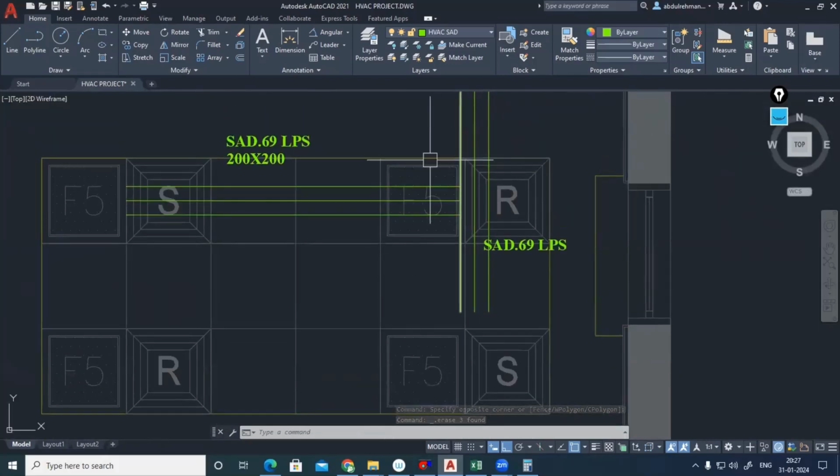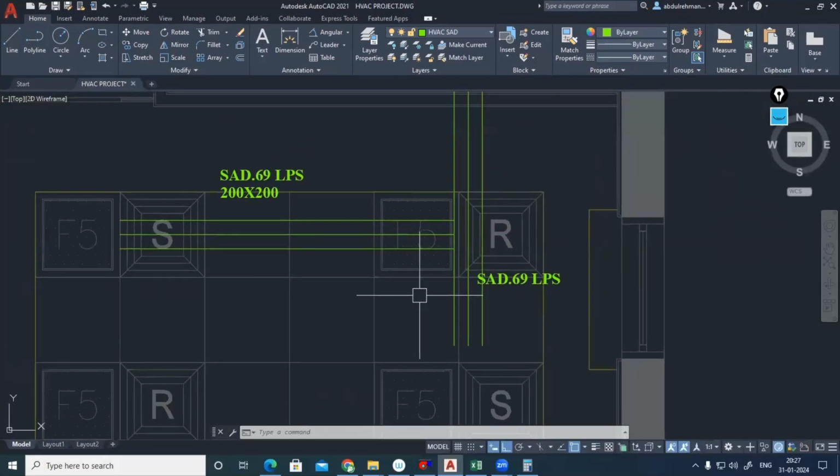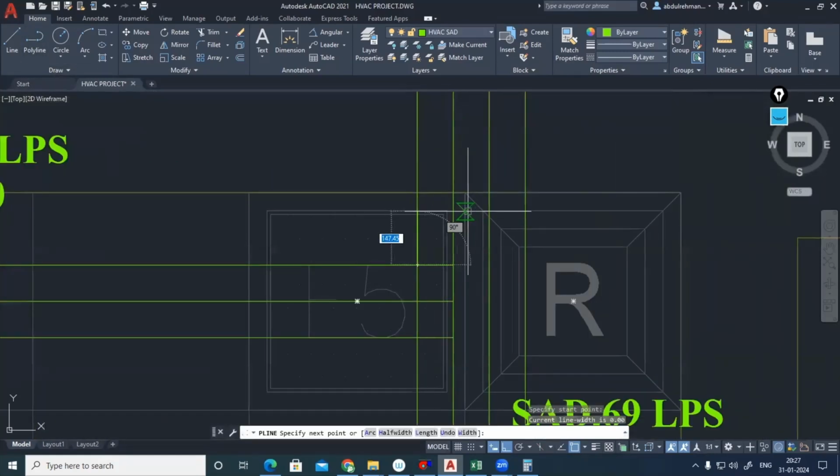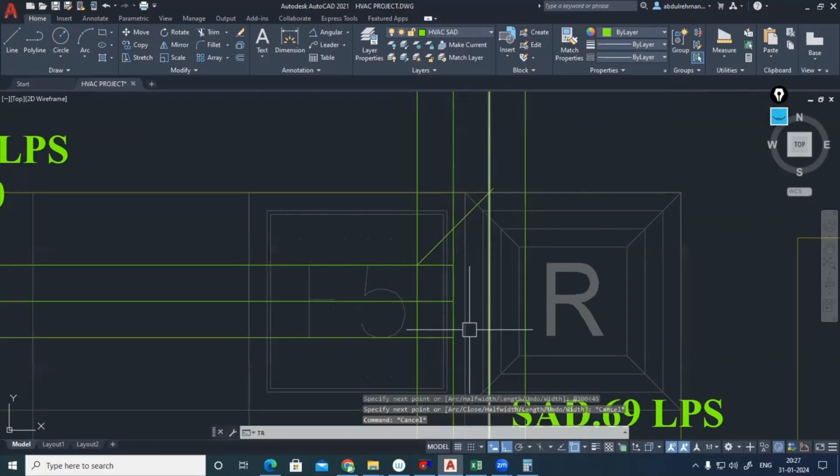Fine. Like I'll be offsetting this one. 100 is fine. Oh, and 100 mm enter. I'll be offsetting this. And this distance I need 45. Shift at approximate distance, angle 45. Here double enter.